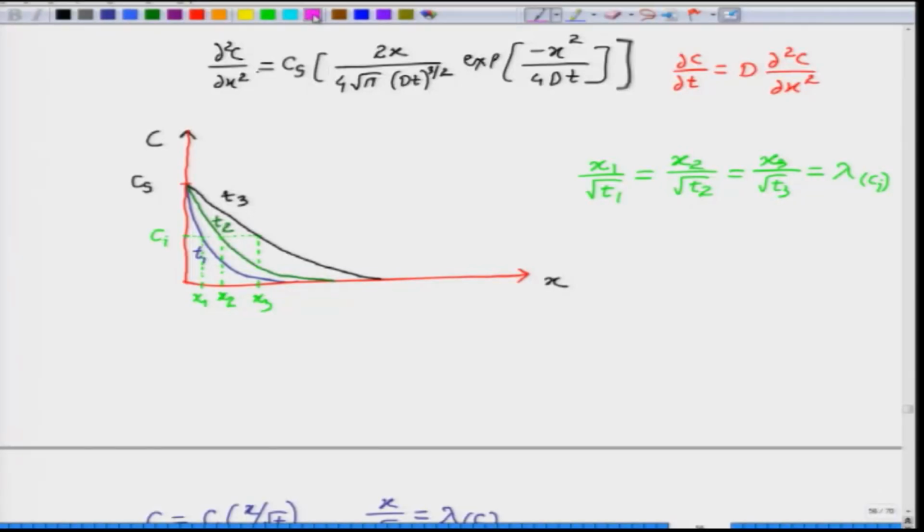So, for example, if we had designed the process for a case depth of 500 micron, so x1 is equal to 500 micron, and the carburizing heat treatment time for attaining the 500 micron case depth was let us say 4 hours. But now we want a case depth of 1000 micron.